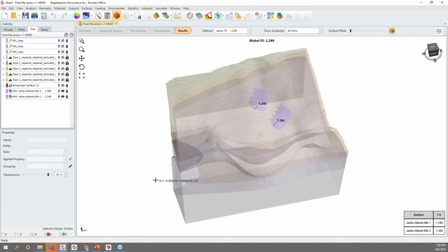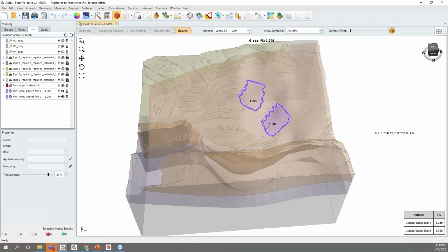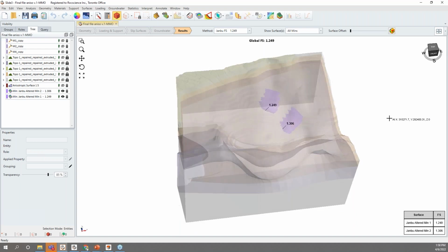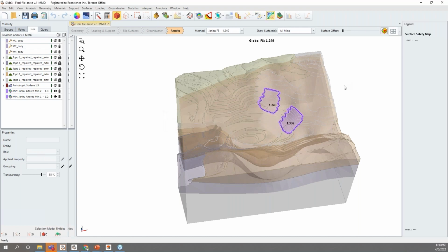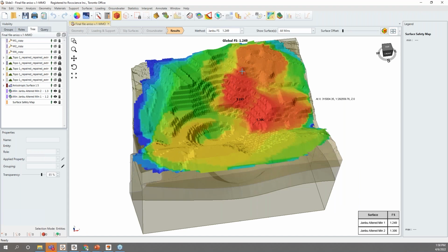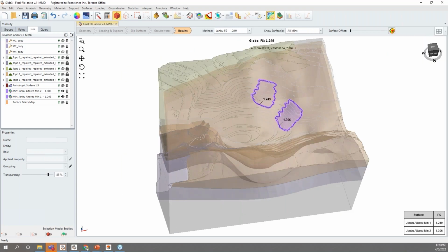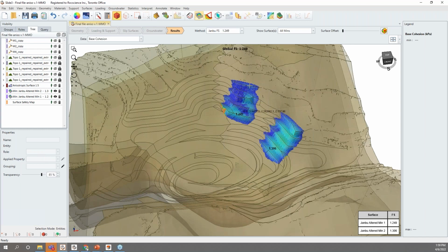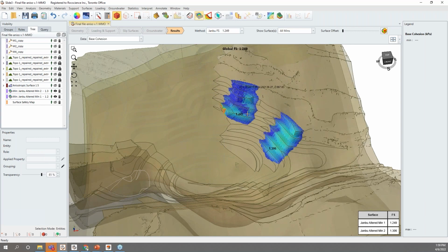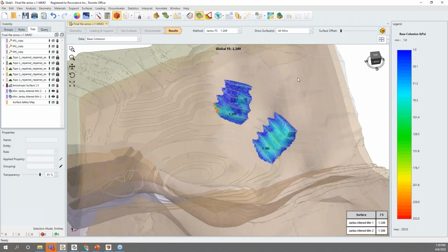And here is the results of multimodal optimization. So you can see that if you do multimodal, you can find a weaker region because the algorithm is slightly different from the PSO itself. And the multimodal actually found a better one, a better critical slip surface, a weaker region on this side. And let's investigate the reason. The reason is this. So if we look at the contour for this lower factor of safety that multimodal found, you can see most of it is that dark, low cohesion.